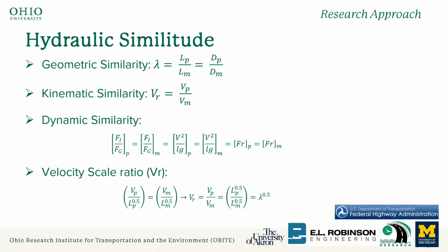If we want those forces to scale correctly, we have to use the Froude scale, and that's where the velocity becomes scaled by a square root instead of by a linear scale like the geometric scale is. Hope that answers the question.